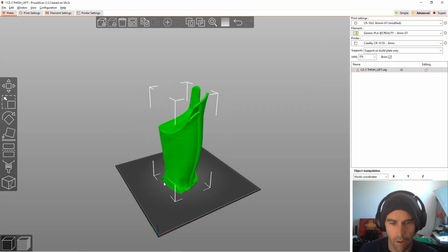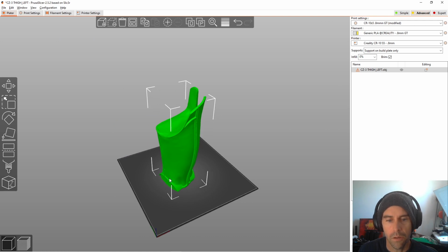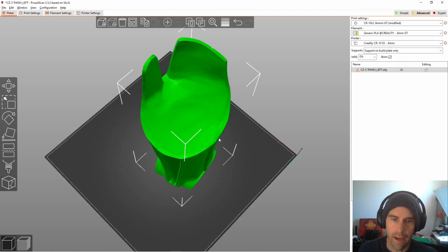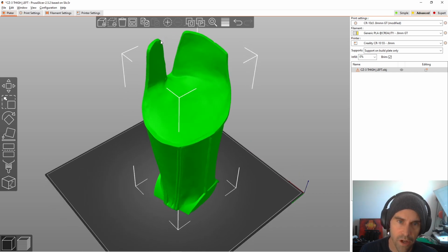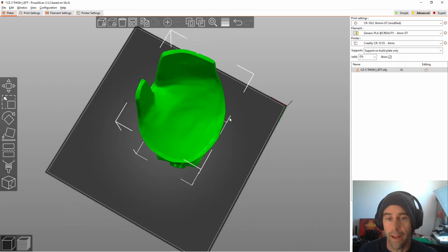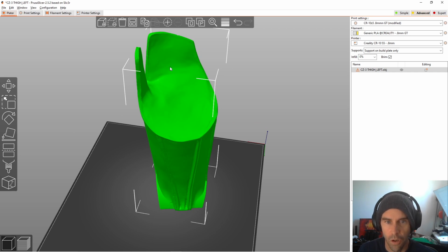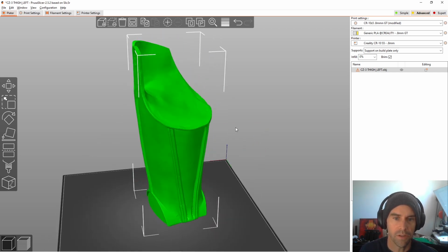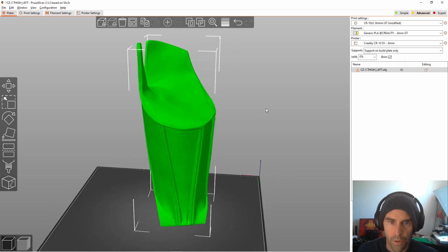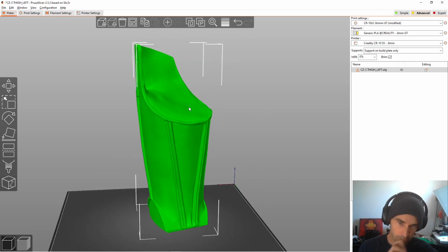So we're going to look at the part here because people ask about how I close the part up. Basically what I do is in ZBrush, I select all this inside wall and just remove it. And remove the inside here. And then I hit close holes, and then it bridges up all of this. Now I kind of had to sculpt this. You can tell it's been sculpted a little bit, and it wasn't very careful because it doesn't matter. You have to kind of re-sculpt this stuff into a shape so you don't have like a big blob.